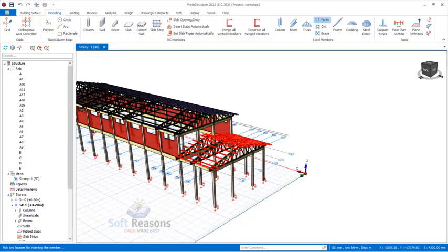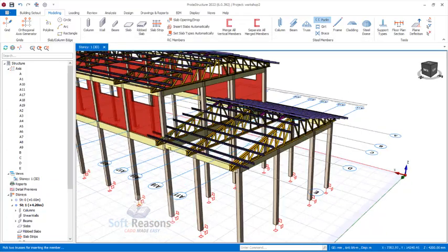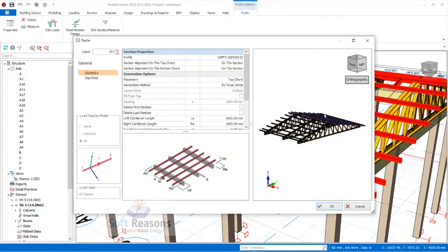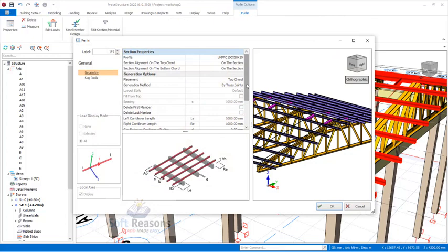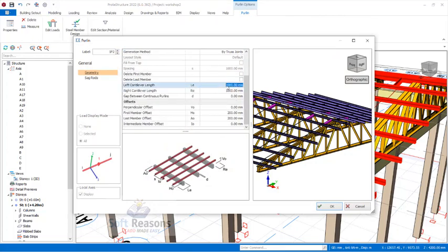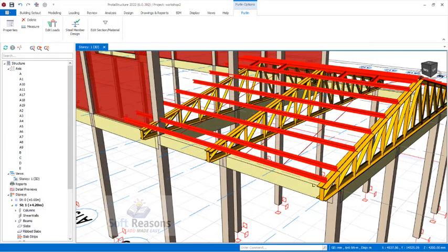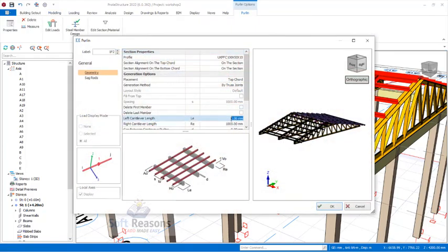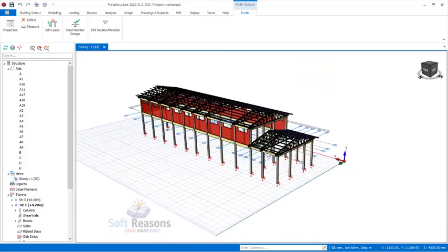Okay, in this case we wouldn't need the cantilever, so you have to double click. Which of the sides are we considering? It seems to be the left hand side. Let's try this and see. Click on it. Okay, so that is this side, so we wouldn't need the other right hand side. You provide 100 meters right there and change that provision to 0. Click on OK. So we have something of this kind.